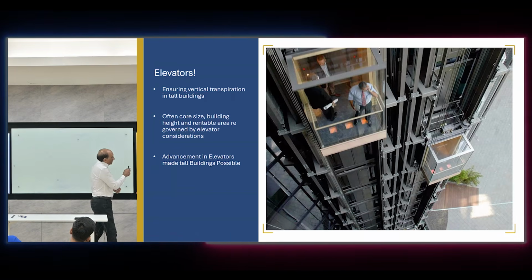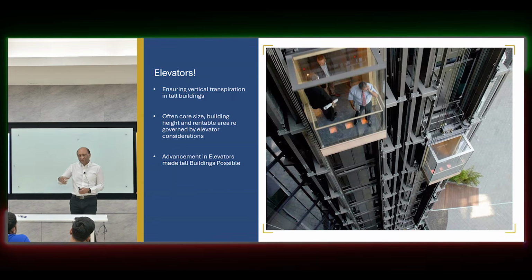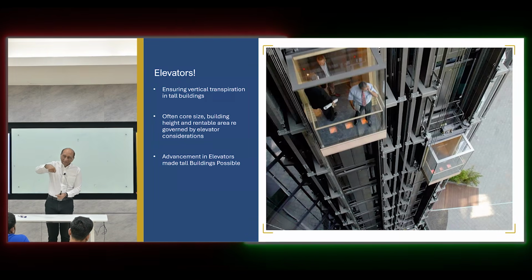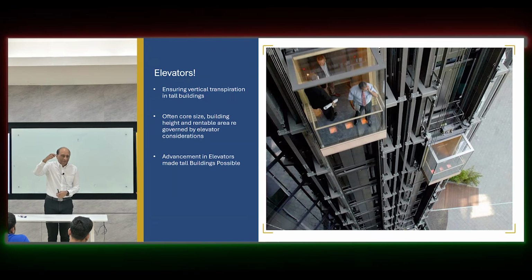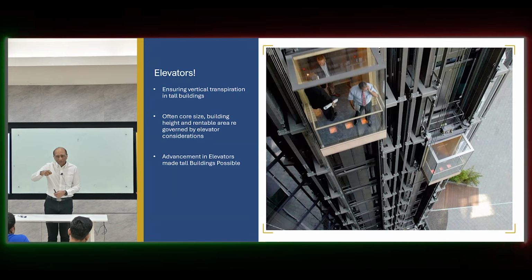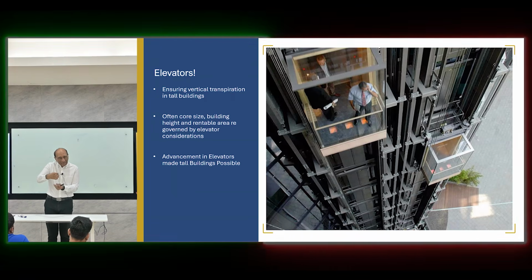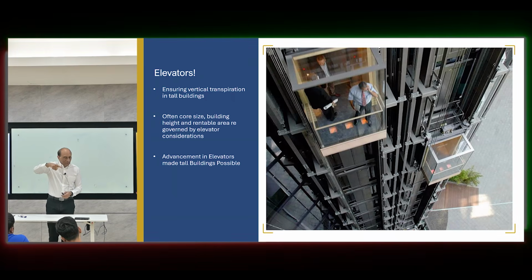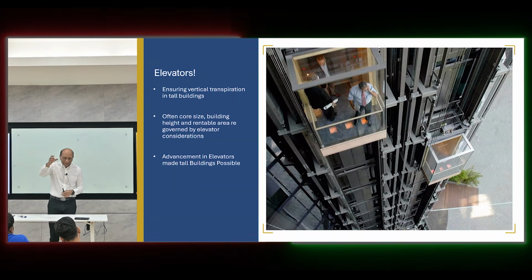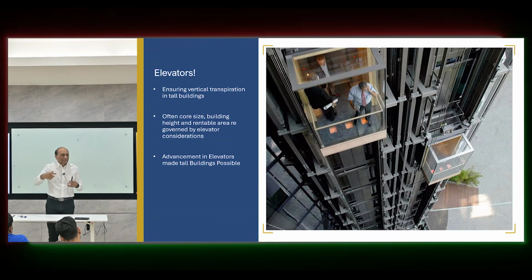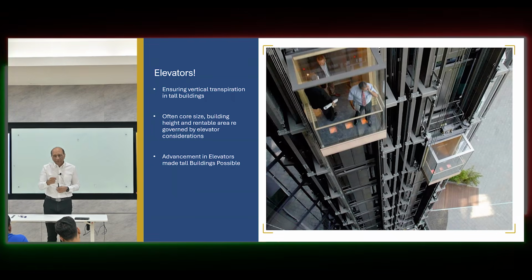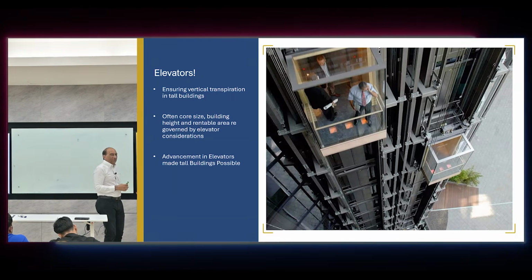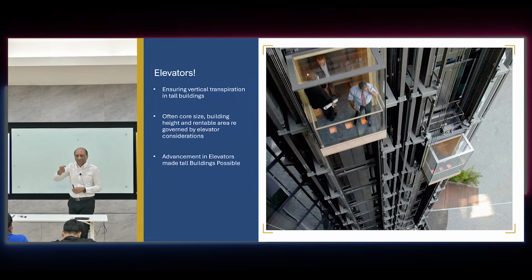Now, in the past, and still in many buildings, the elevators use steel cables. But for steel cable, if you remember course number 1, we have the specific length or specific height. After a certain length, the cable becomes so large that it is impossible to roll on a drum, because the cable has to roll when the elevator goes up and down. Practically, the cable becomes so thick and so long that you cannot maintain it. And that is the limit on tall buildings using traditional steel cable elevators.